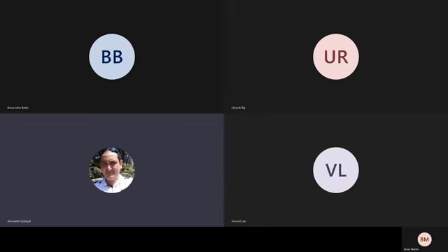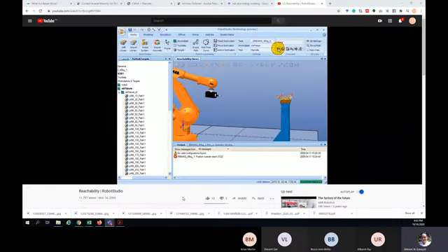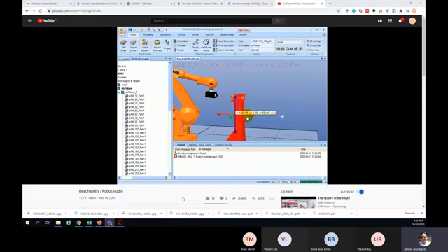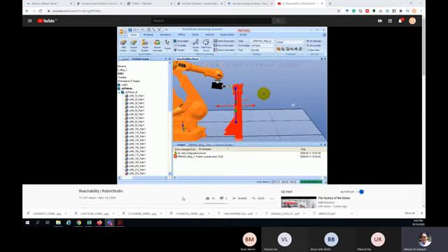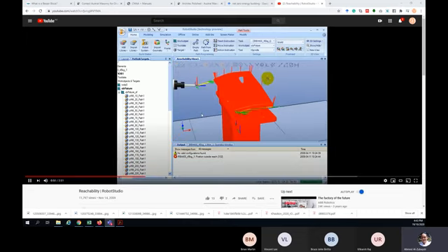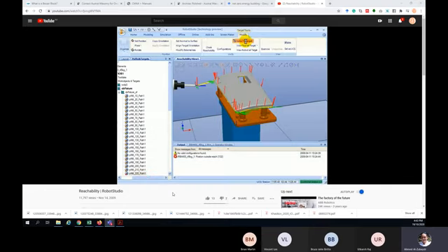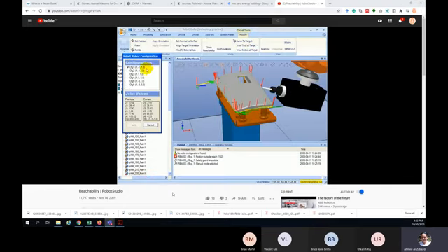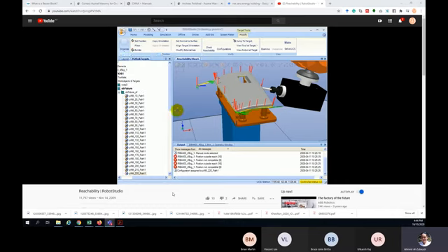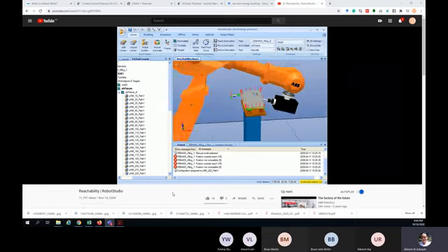So this example about testing the reachability of the robotic arm: you can make any CAD model separately in SolidWorks, but you have to save it in a different format and bring in a robotic arm. You can even make this handle, or find it online with the video I sent you. At the end of the video, you can find the suction port, or you can use the welding tool available with Robot Studio.